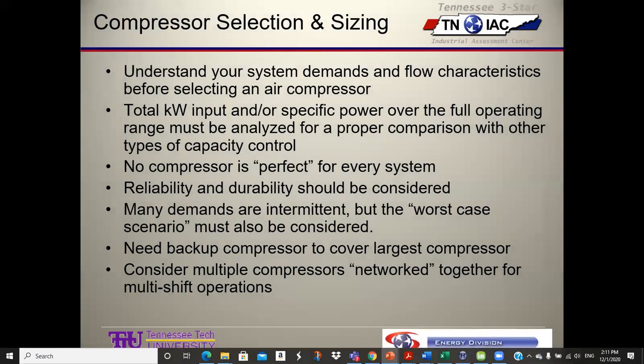Understand your system demands and flow characteristics before selecting an air compressor. It does take a lot of study to figure out exactly what compressor would be best when purchasing one. Total kW output and/or specific power over the full operating range must be analyzed for a proper comparison with other types of capacity control. I mean, the VFD is great, but if you're going to run at 100% load, it hurts you. And it also adds a lot of expense to the compressor. So if you don't have any VFDs, then it might be a good option.